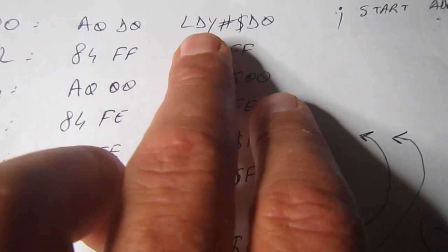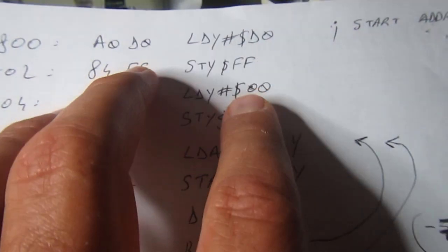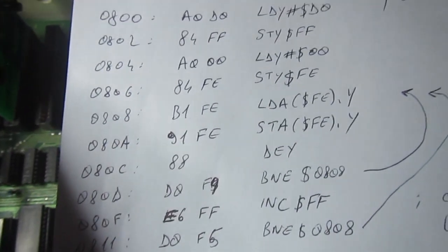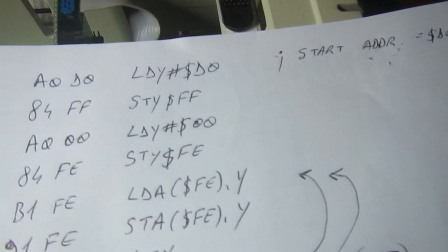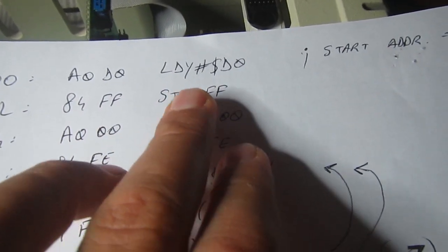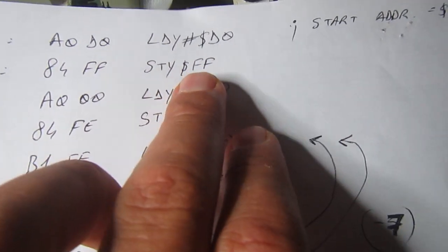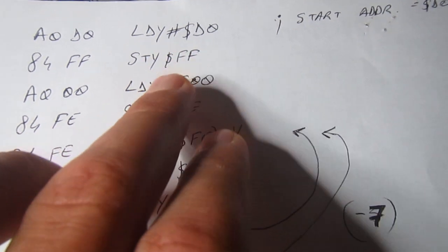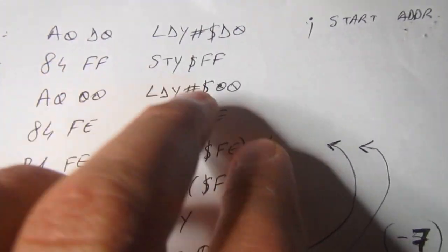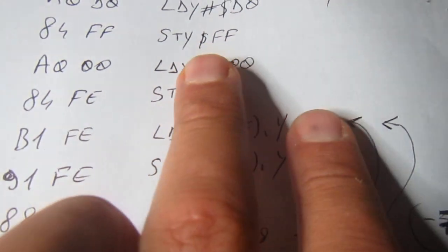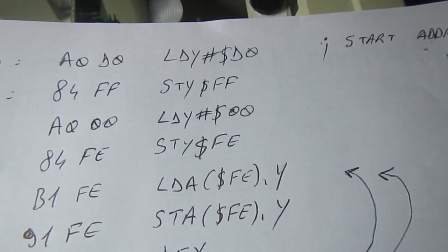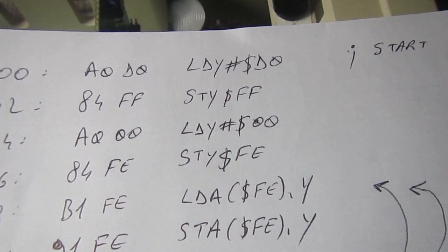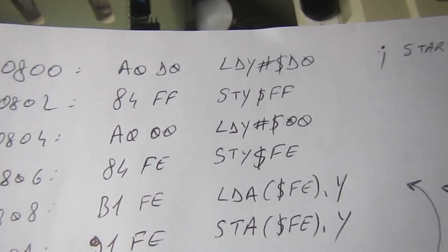So what we want to do is copy all the ROM space into the RAM. ROM space starts at D000, and on a 6502 the addresses need to be reversed. So in the last byte of a page 0 location, we write the most significant byte of the address, D0, and I chose just FE and FF, the last two locations of page 0, to store the address. I don't know if they are used by BASIC or something, but I think it works.